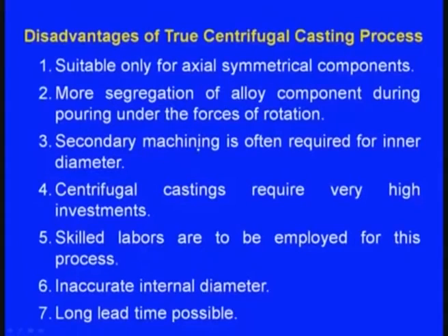Next one, secondary machining is often required for the inner diameter. Yes, on the inner surface of the casting, all the impurities will be collected because they are subjected to lesser centrifugal force. So, these are to be removed, and sometimes machining is required.